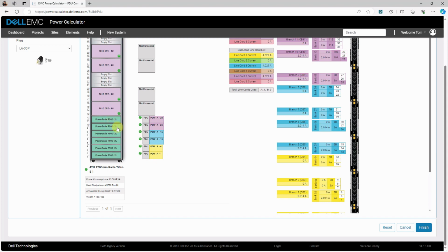So now you can see these guys visually through the power cords: 1 power cord, 2, 3 power cords. If I was to lose an entire power cord, I wouldn't lose more than 2 of these nodes. Keep remembering, when I say I lose them, I'm just losing half the power to these nodes. So that's what would happen there.